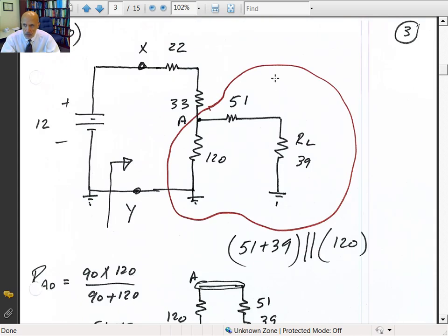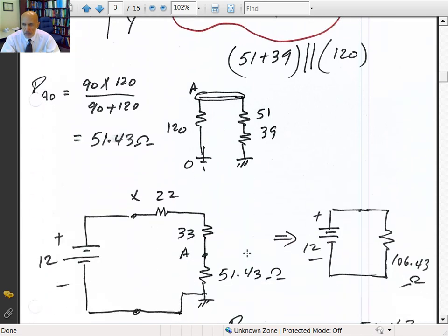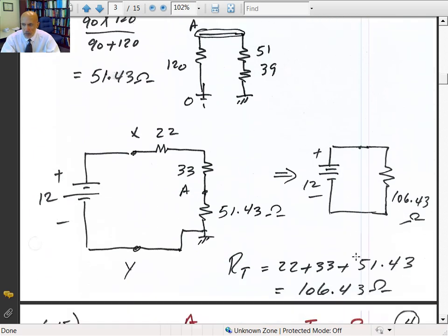So that part of the circuit could be replaced. Later on, we're going to look at the technique called Thevenin's, where you can pick any points in a circuit. If it's unknown, you make a couple of measurements, and you can come up with equivalent circuits. It's like a voltage source connected in series with a resistance, which is a very powerful method in the modeling of a circuit at any given point in a circuit.